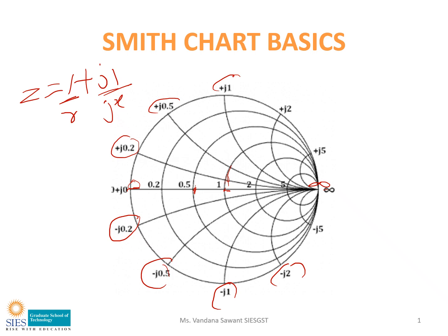To plot this point, first we have to find where the r equals 1 circle is on the horizontal line. This is your r equals 1 circle, and as it is plus jX, we have to move on the r equals 1 circle in the upward direction. Similarly, the jX value is plus 1, so we need to find where jX equals plus 1 is, this one.